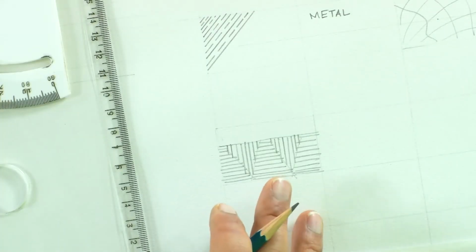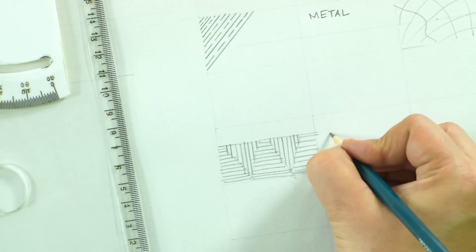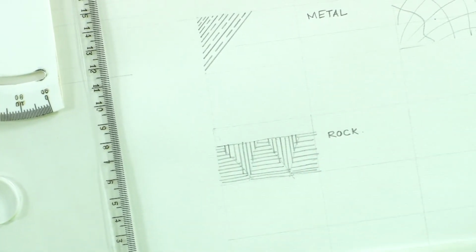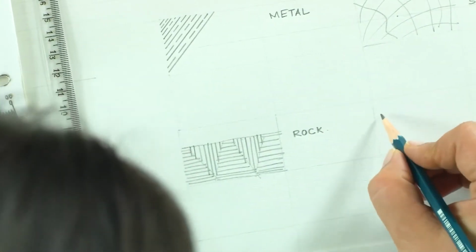Suppose there is a rock section. In case the drilling is being done and you have a very deep pile foundation which is going to be used, then how we represent rock sections is that we will have this combination of hatching, a vertical and a horizontal hatch which will be placed together. So, this is what we use for rock, and then for insulation, again we have